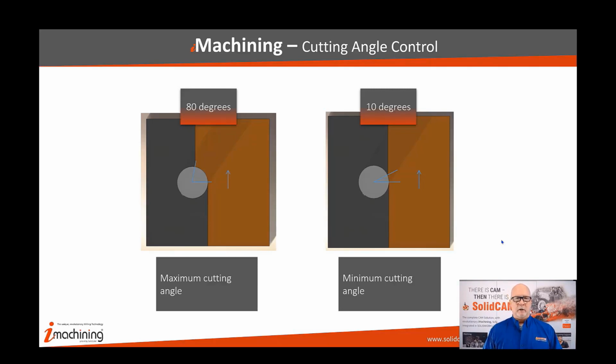And so we kind of determined that's the area where that vector begins to start sweeping to the outside, and we wanted to stay away from that. There's not a lot going on between 80 and 85 as far as performance and productive work. So it was better just to keep the tool down at 80 and keep it in a very smooth and very clean area and not have that vibration.